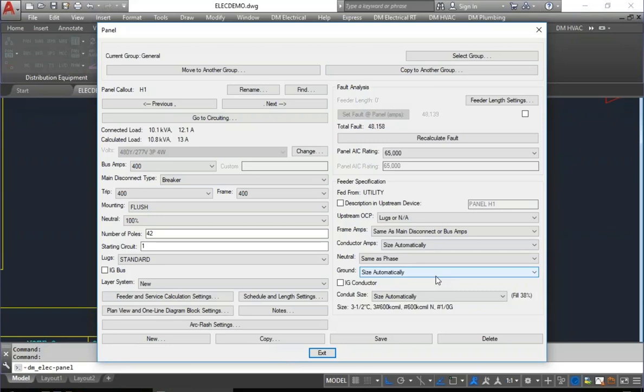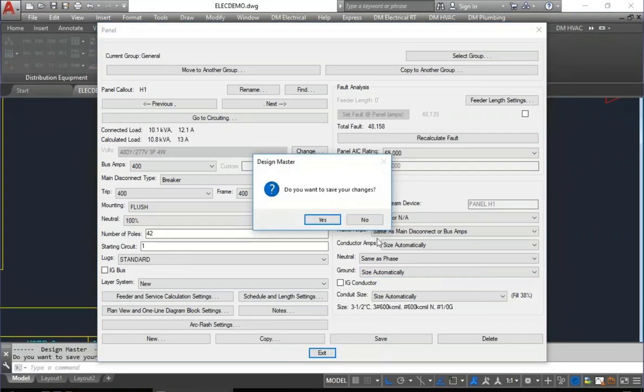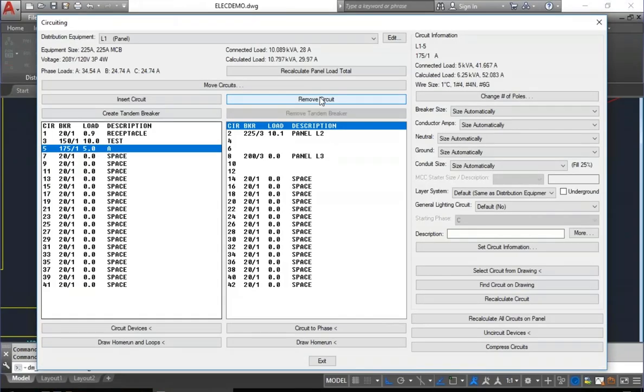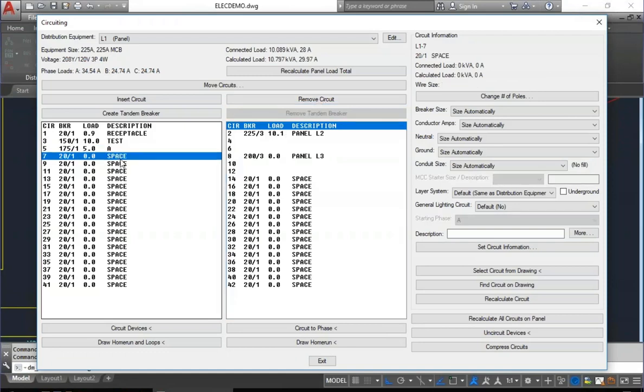New in the most recent release, when you upsize your conductors for wire size, we upsize the ground proportionally as well. Previously, we didn't adjust the ground. So if you upsized your conductors, you needed to upsize the ground as well. Now we do that automatically, and it's proportional to the change in the conductor size, which can lead to some unexpected results if you're not really thinking through all of the different changes.